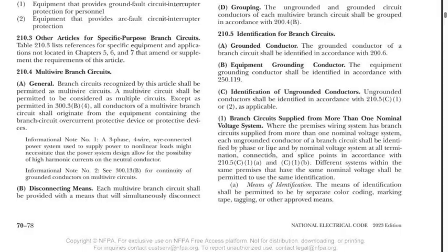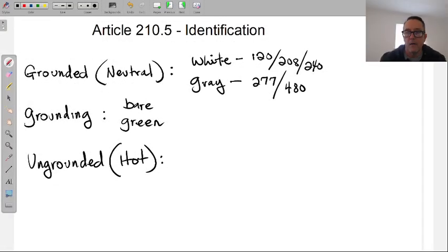Commercial and industrial buildings usually want 480 fed into their building. All right, Ohm's law is why. If I have to connect a motor, if I connect it to 480, when the motor is operating, it draws less amperage. If I connect that same motor to 208, which 3-phase motors allow you to connect to either of the 2 voltages, Ohm's law happens. If I connect to 208, then the amperage goes up.